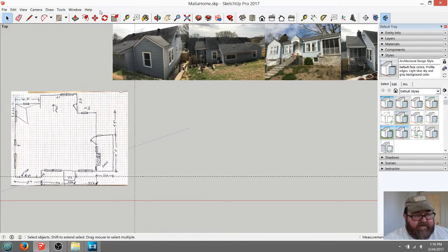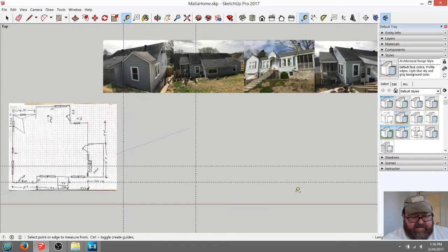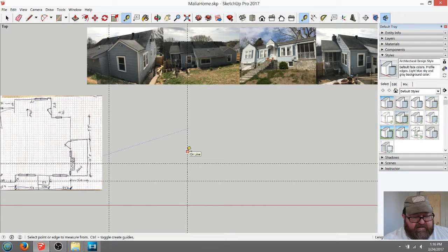So looking at my drawing here, I've got the actual drawing in front of me. It's 12 feet 4. The garage area down here, this little offset right here is 12 feet 4. Then it goes back 2 feet 9. And I'm just drawing myself some construction lines here. It looks like I'm going to have to move everything back, but I can do that in a minute.